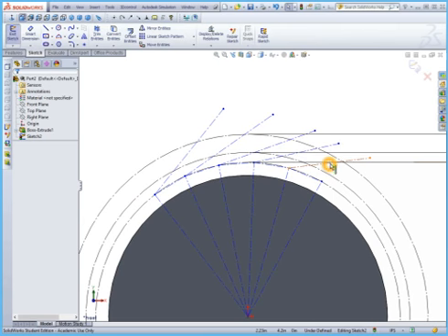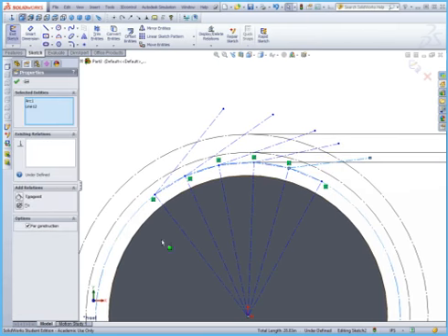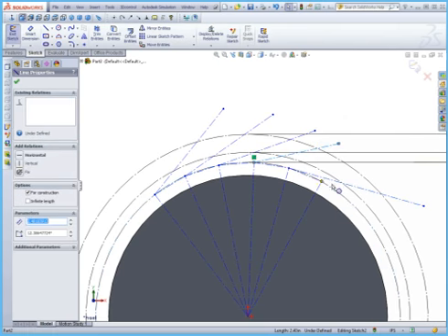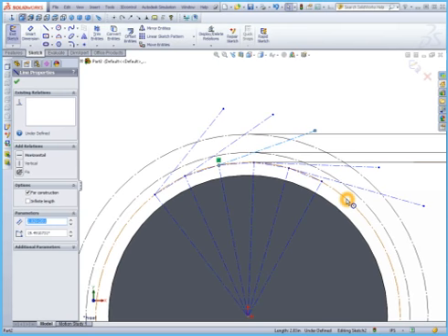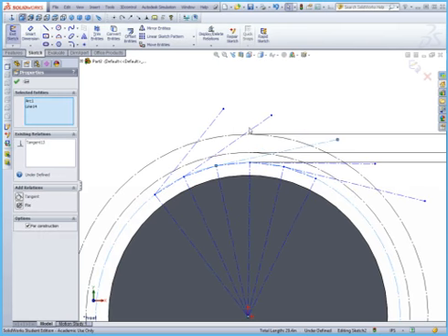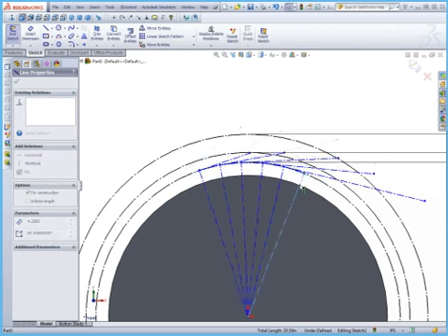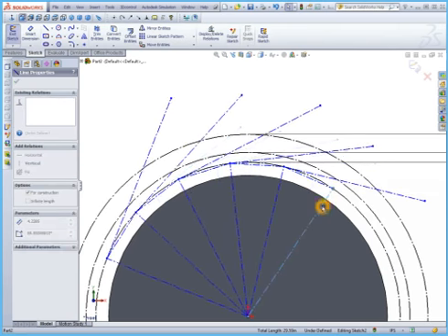So in SolidWorks, if I click on a line and I click on the circle that I want it to be tangent to, I'm given several options. I'll pick tangent. Note that it actually changes the length in this instance, so we'll resize these correctly later. So now all of our lines are tangent, and again, if we move this system, those relationships are preserved.